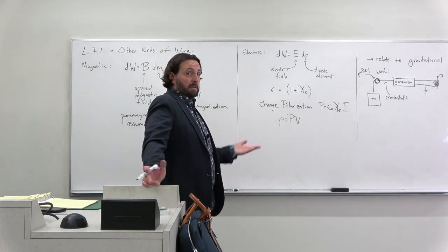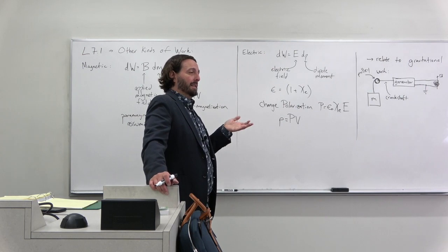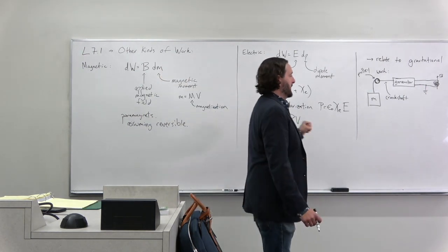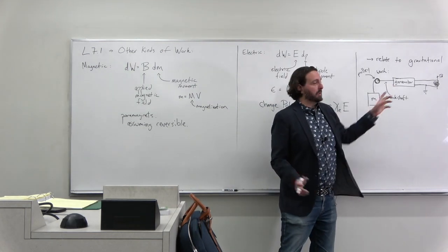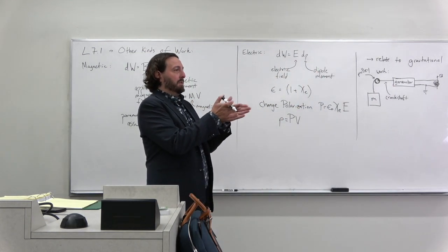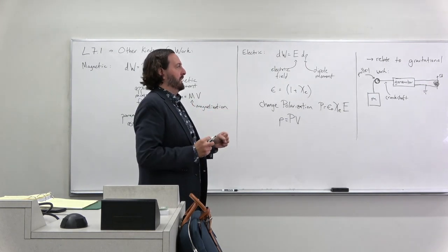And then that's going back to your battery. So that's actually exactly how the regenerative braking on a hybrid vehicle works, right? It's actually engaging this generator when you apply the brakes. It doesn't actually push off like dissipative work like you used to. Now it actually engages, say, the magnets of a generator.